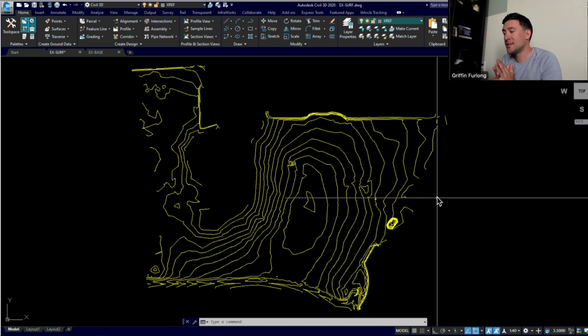Why? Well, let's say you overlook an existing ditch that's carrying 300 cubic feet per second of flow through the middle of your site. No worries, you'll just cut it off, right? And you'll build a berm around your site. Well, no, because the water has to go somewhere. And since it's a high discharge, you may have missed a big cost of installing large culverts, head walls, and